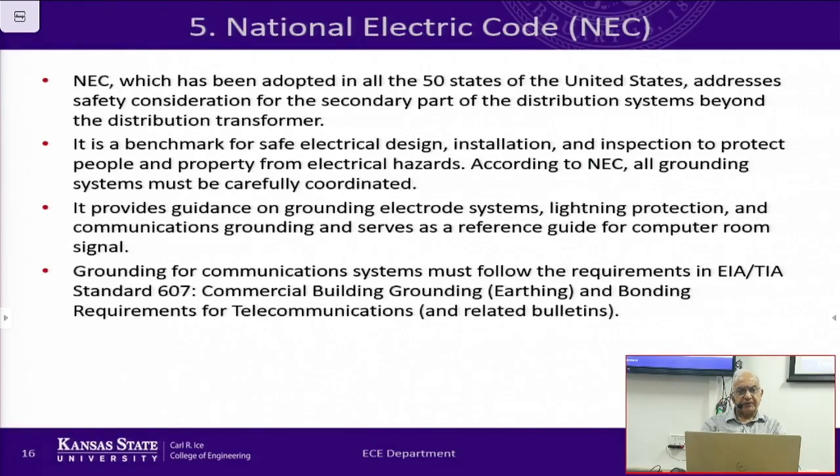So this is something extremely important for people who are architects, who are designing buildings, because architects not only have to design an aesthetic looking building, but they also have to worry about how to put wiring inside the house, and how far apart. For example, in the US we have a rule that inside a house, in any room, for the receptacles that you put for plugging in devices, 6 feet is the maximum distance allowed.